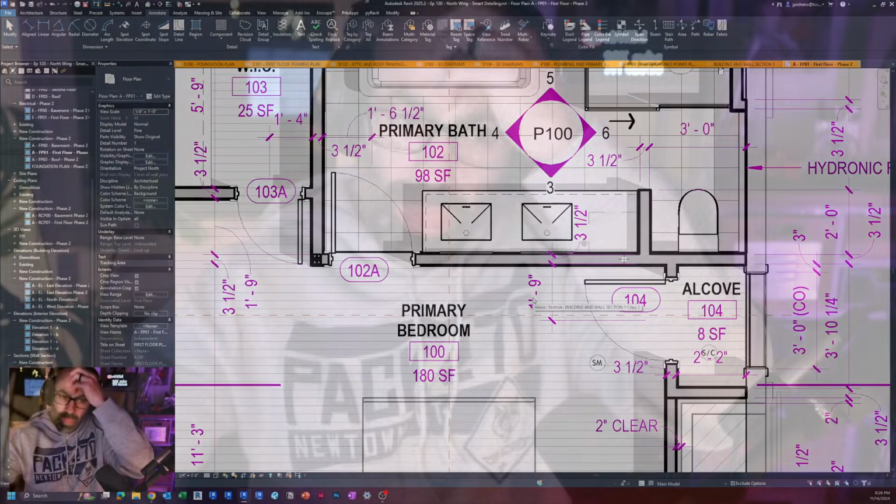The benefits of this are obvious, right? You can definitely generate the views quicker and tag quicker. You're not typing it or copying and pasting it and aligning it and so on. But also, if you're changing that note, it's changing it for that element everywhere. You're taking advantage of the information, the idea of BIM, the second you use a tag.